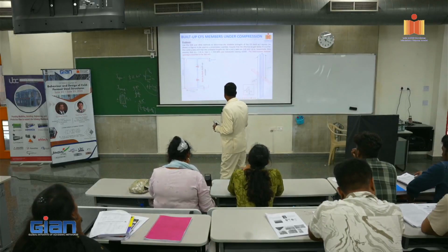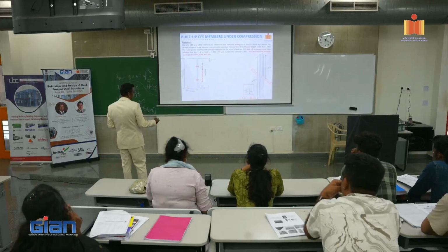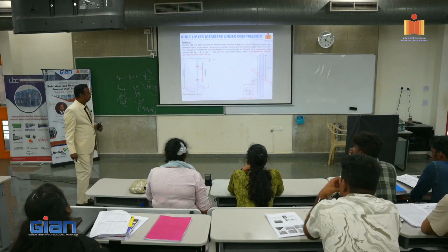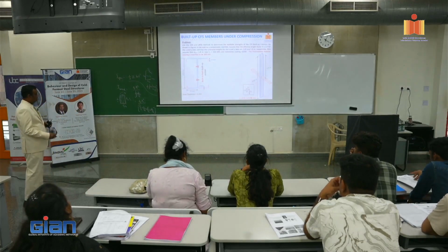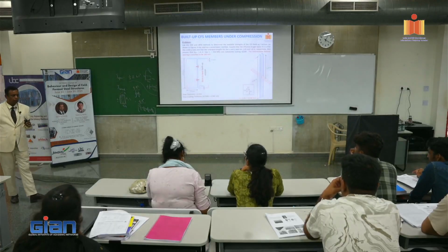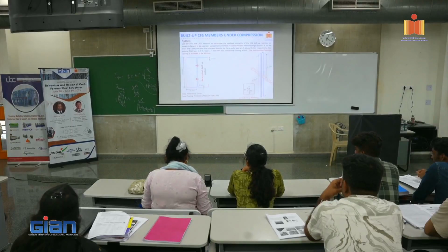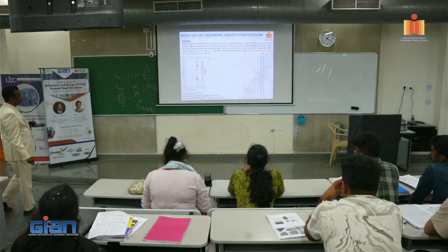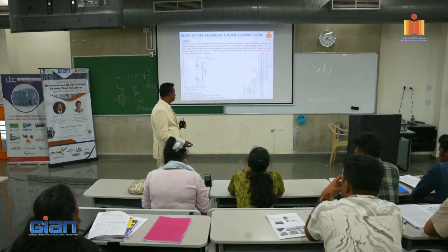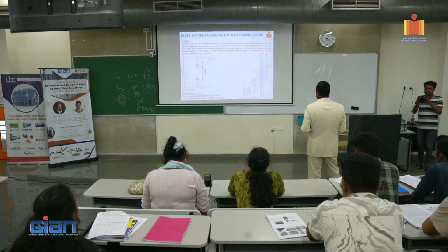Now we know that R is 1.5 T, right? We know that T is less than 2, so it becomes 2.94, right? How do we do so? Because the total thickness is 2 mm and the coating thickness is 0.043. Hopefully you have been taught 0.043, right? How to calculate the total thickness. Now base metal thickness is the actual structural thickness, right? That becomes 2 minus 0.043, it becomes 1.957, right?